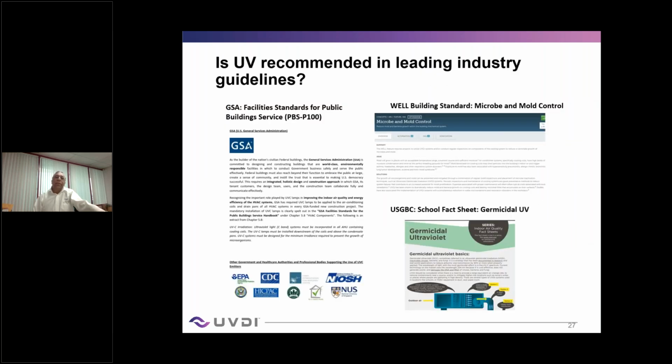So UV has been recommended by ASHRAE for a long time, and GSA spec has been there for a long time. And there's a facility standard, PBS P1000. Chapter 5 talks about using UV for coil cleaning as important to improve your indoor air quality.